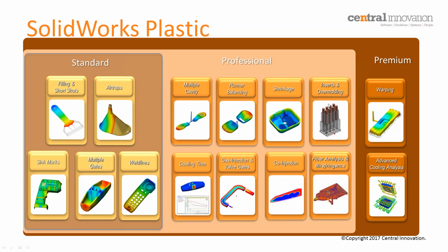If we have inserts or overmoldings, we can do that. If we have co-injection, we can understand the fiber analysis. We can have gas injection and valve gates, and we definitely can understand the cooling time. But at the Premium level, we go to very advanced manufacturing feasibility tests, such as warping and advanced cooling analysis.